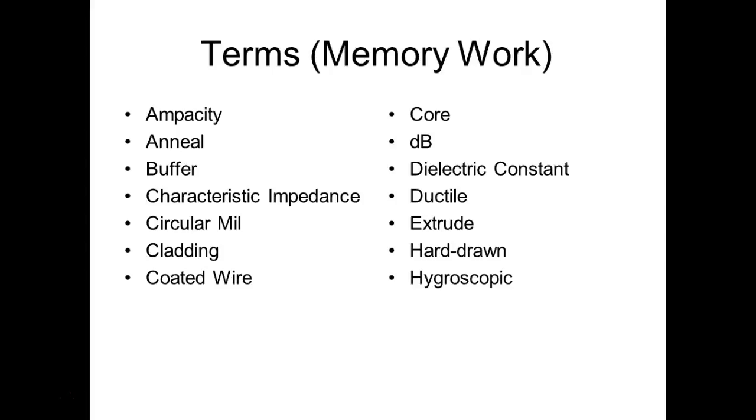We'll talk about that. Understand that most of the time when we have loss in a communication cable, they use dB. They don't use volts. It would be hard for me to say I'm going to lose this much voltage, because communication cables carry different voltages, right? But if we knew the dB loss, we could calculate the maximum dB loss. We could calculate the voltage drop loss over that cable.